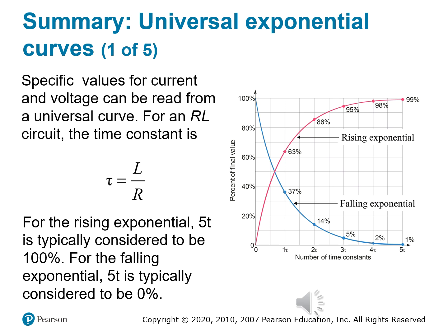In an RL circuit, the time constant we define as tau. Tau is equal to L divided by R, right? Inductance divided by resistance, where L is inductance in henries and R is resistance in ohms. Tau tells us how quickly the circuit responds. It's the time it takes for a signal to change by about 63% of its final value.